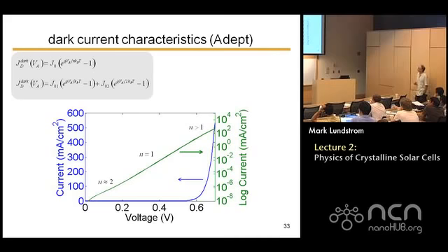And that might be series resistance, or it might be high-level injection, or it might be a number of other things. Okay, so here's the simulated IV characteristics of that silicon diode that we're looking at, that green solid line. The green solid line is on the log plot on the right, the blue line is the linear plot. And you can see a nice clear n equals 1 region. You can see a hint that there's a region where it's trying to go above n equals 1 at low bias, the way we expect. And you can see a little bit of roll-off at the high end, which we expect also.